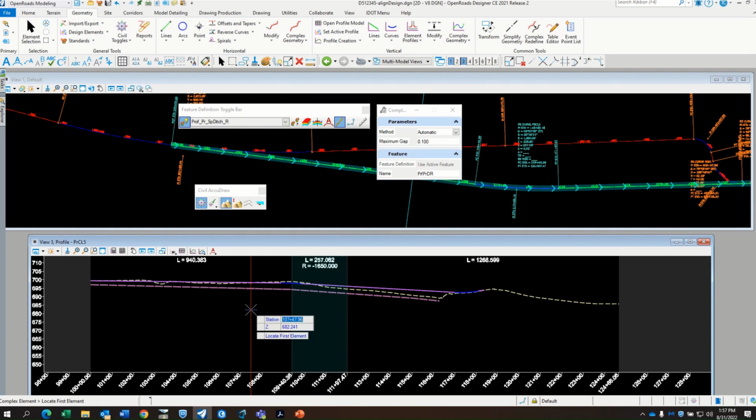Now here, we're not going to make this the active profile though. That was really just for the roadway profile. See, what would happen here is, because there can only be one active profile, so this is a little confusing here, because normally you think of, well, once you're finished designing the profile, you make it active. But if I was to make this active here, what would happen then is the roadway profile would then use the special ditch profile, and that's not what we want. So I am not going to make the special ditch profile active. We'll leave the roadway active.